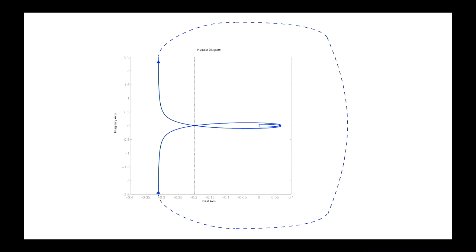All right. So our open loop transfer function, lambda s, is equal to C of s times G of s. Our C of s is 1. Our G of s is e to the minus s tau on s. And if you look at this at low frequency, so really the Nyquist plot is just a polar plot of lambda j omega.